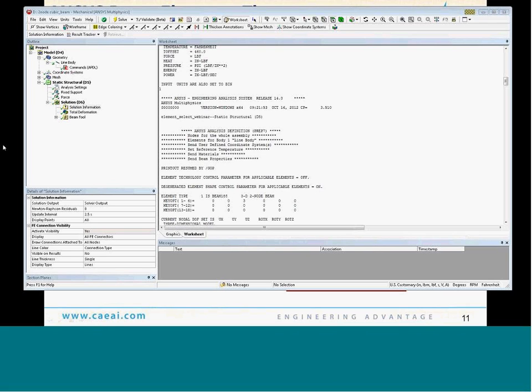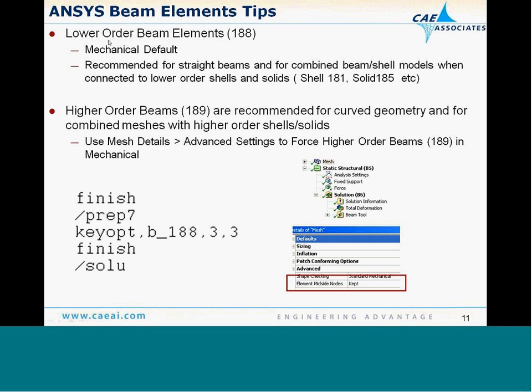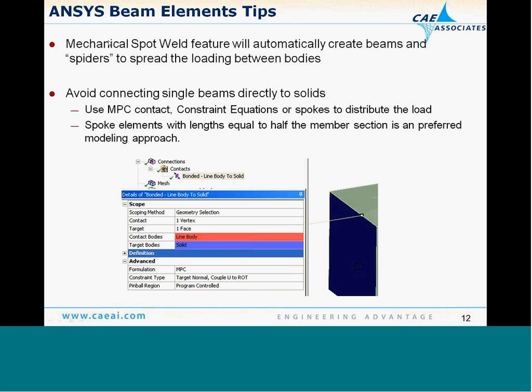We'll go ahead and move on while the poll's closing. Going back to my PowerPoint presentation, notice in the results that not many people use a single element type, but there are some people that use shells and solids. So one thing to consider might be putting beams into your model where it makes sense and where it's advantageous.